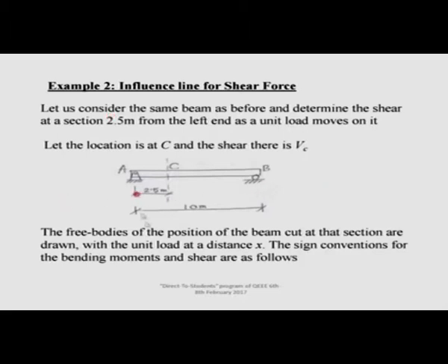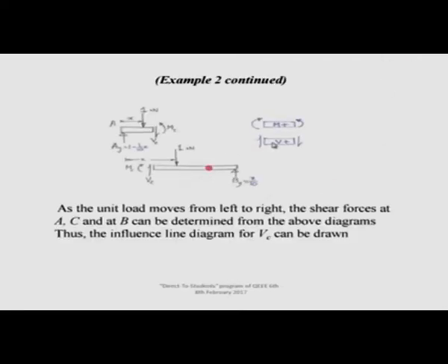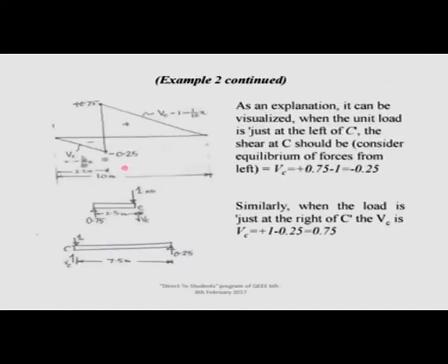Now, see the shear forces. I need not explain in much detail, because we just need to know the statics. I need to draw the free body diagram at a section. If the question is how the shear force changes when a unit load moves onto the structure, I can have the unit load here, take a section for different parts of the free bodies, solve the static problem with my sign conventions, and then find the shear forces as the unit load moves, and we will land up with this kind of diagrams.